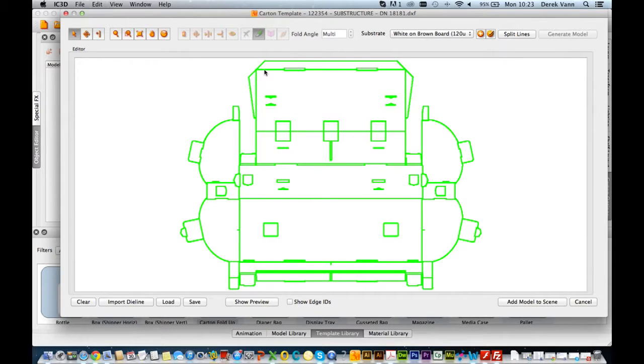The middle lines can now be selected individually, but by holding down the Shift key and clicking, you can select several lines which are collinear along the same length. These lines can be linked together as folds using the Linked Folds button in the toolbar shown orange. When an angle is applied to one of these folds later on, they will adopt the same angle. The side lines are not collinear and so cannot be linked.